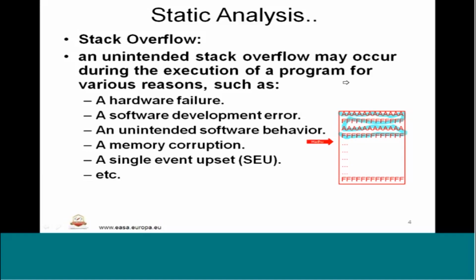For simple programs it will be easier, whereas if there are complex programs, definitely we need to have a thorough stack analysis, especially in Level A software. Level A is the most critical software used in aerospace embedded software. So in such cases, when a stack overflow occurs during the execution of this Level A software, the consequences could be catastrophic, as the software may be out of control. We cannot predict. Definitely we cannot afford to have an aerospace vehicle, when it's flying, having trouble with the stack. Definitely that needs to be analyzed appropriately.